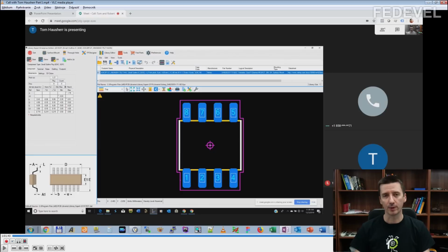Always when I'm designing footprints for a chip, or not always, but sometimes, I had this question: do I need to use local fiducials? Maybe you have seen this on some boards close to a chip. There are local fiducials. I don't really use this on my boards, and I have never had any problems with this. But I always wanted to know if we should be placing these local fiducials into our libraries or not. So I had the opportunity to ask Tom, and here is the answer.